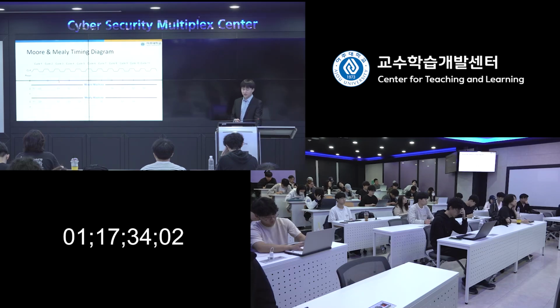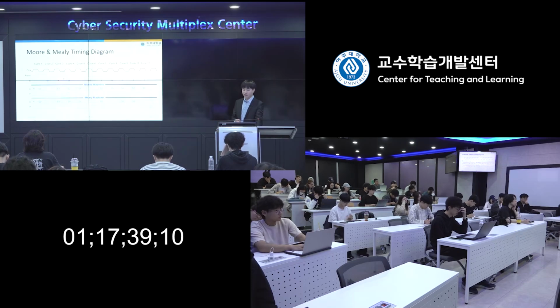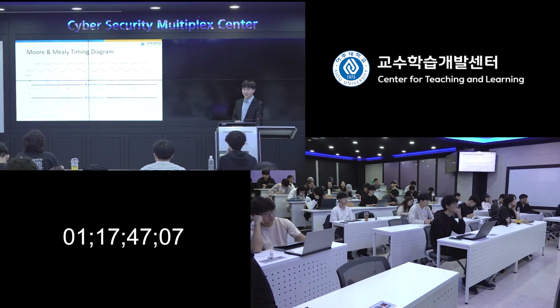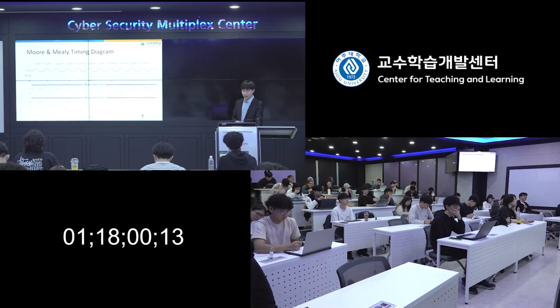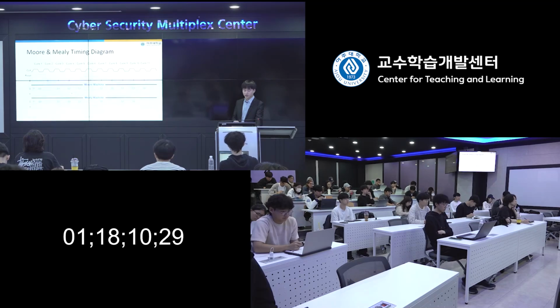At the next check, A becomes 1. Oh, this is the pattern we just did, so the state also needs to switch. It will trigger both machines to switch to a new state in the next cycle, S2 and S0. So in this case they will output 1, right? You would see that the Mealy machine outputs 1 at this moment, and the Moore machine outputs 1 only after cycle 4.